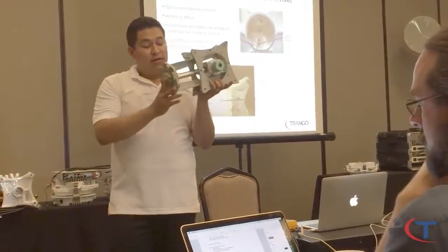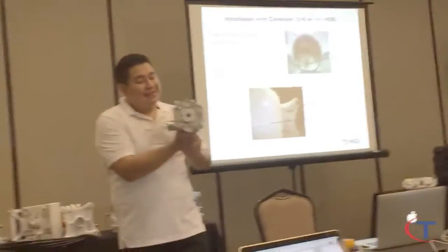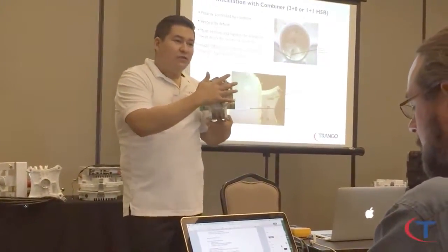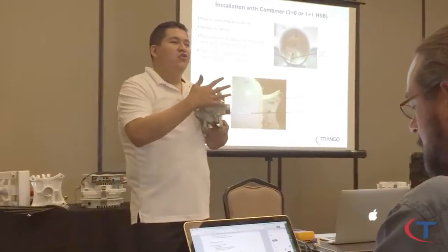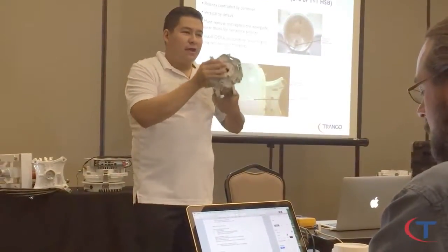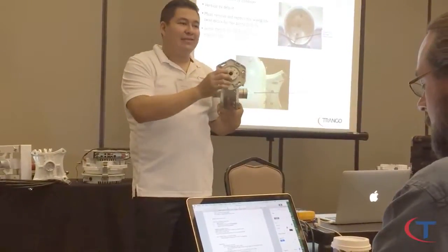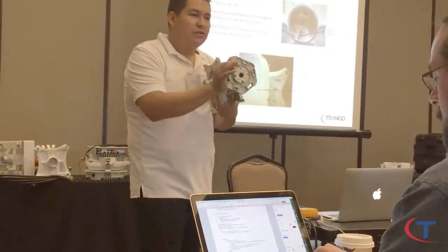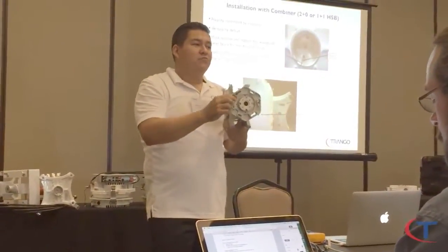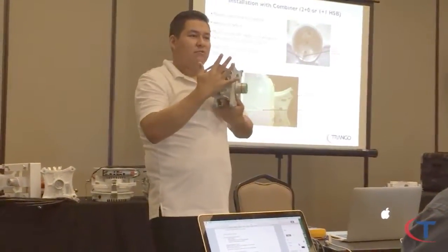Okay? Also, seating this on the back of the antenna: if this is not well seated and mounted properly on the back of the antenna, your MAC is going to degrade dramatically. So when you put this on the back of the antenna, make sure the seals, the gaskets, everything is in here and it's properly sealed. I don't mean ratchet down all the way until you crack it. No, just make sure it actually seats properly there.